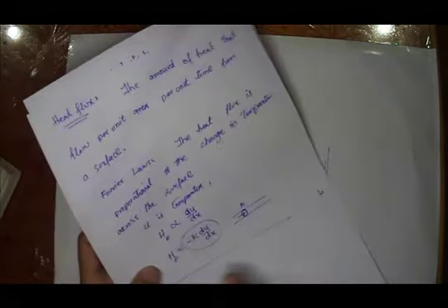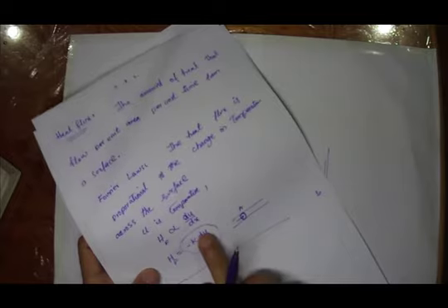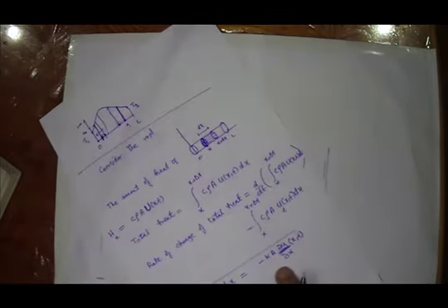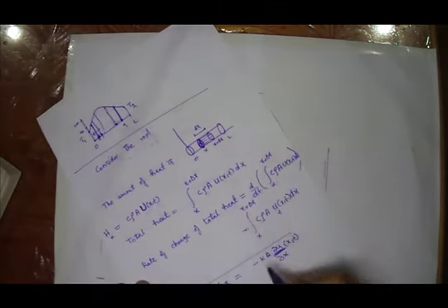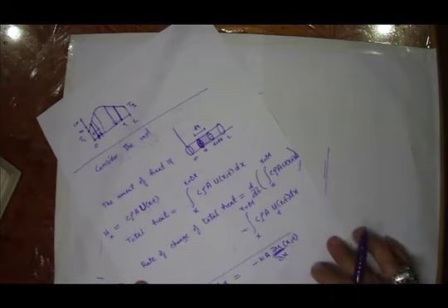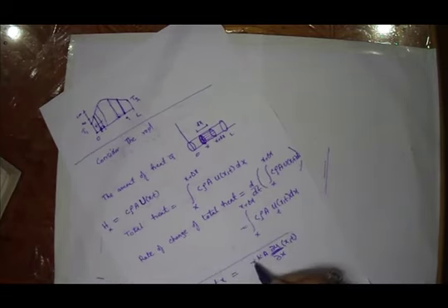When we have unit area, the heat flux is minus k into du over dx. So if the cross sectional area is a, then the heat flux at this specific point is minus k a into partial u over partial x of (x,t). It means